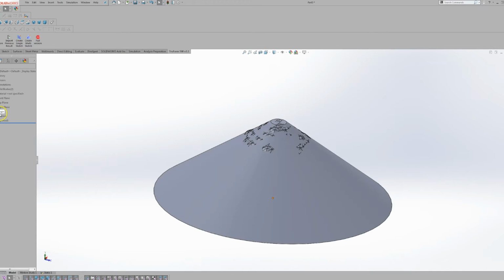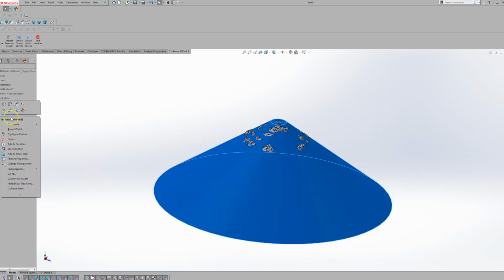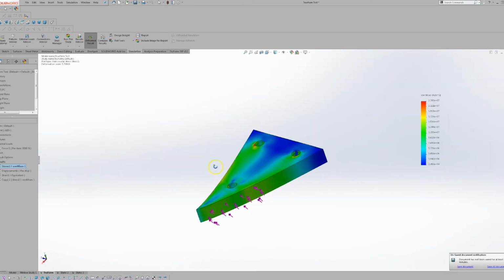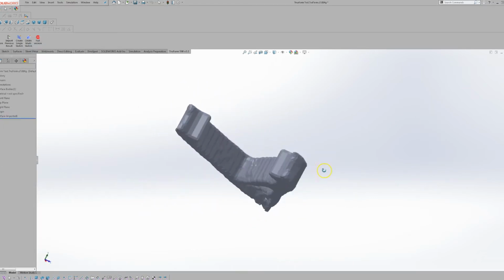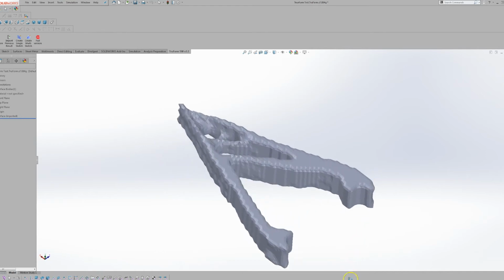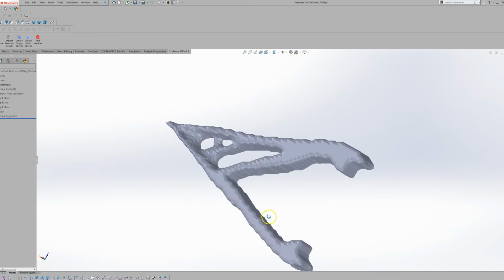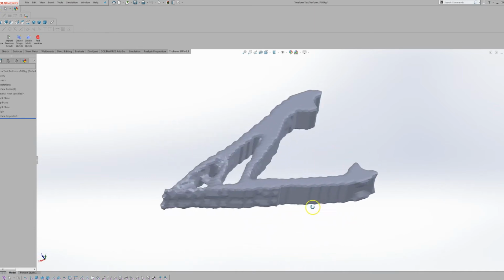Now, Truform Xpress actually provides a range of tools in some of their advanced products where you can sketch over the top and actually prepare the part for a subtractive process like milling or turning. So this is the result of the optimization of that super simplified wishbone arrangement that I did an FEA of. Now it's come out with something really organic looking, it's bumpy, it's fairly irregular, but it gives you an idea of the kind of shape that's required to have the perfect optimization.